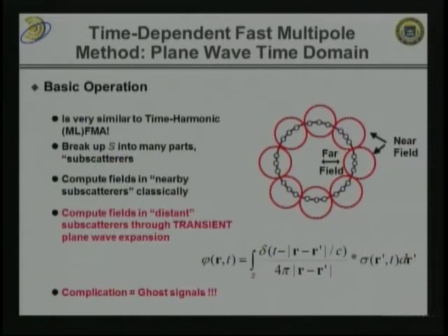Well, again, I'm not going to go into any details here, but for those of you who have never been exposed to this, let me just say that these are hierarchical algorithms that start from a geometry. Here again, I assume that the geometry is a sphere or a circle, and they hierarchically break this structure into substructures, and then they don't evaluate the fields produced by currents here, over there, by looking at point-wise interactions. No, these methods make use of so-called plane wave expansions in order to evaluate the collective fields of sources over here, say over there. Okay, so in a complicated way, they take this original matrix Z, or that combination of matrices Zi that encode fields produced by individual sources, and they decompose them into a product of many, many matrices, each of which is very, very sparse, and which in the end produce the same matrix. That's fundamentally what it is.